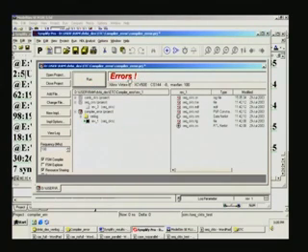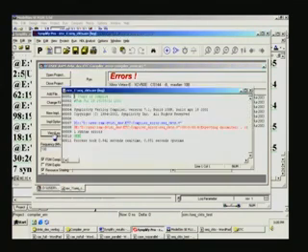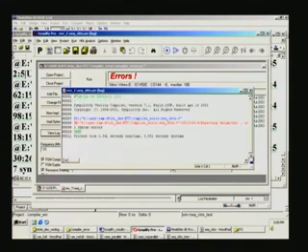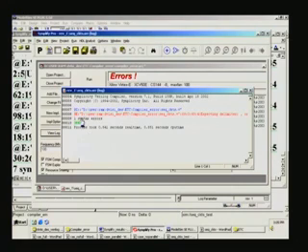It is reporting errors here, and if you view the log file, you notice that it has done nothing beyond that, because at the very first shot it encountered the error, and therefore no further report is seen within this log file, which usually is a very long file. You can see that error is reported here, and what it says is expecting delimiter comma or semicolon.